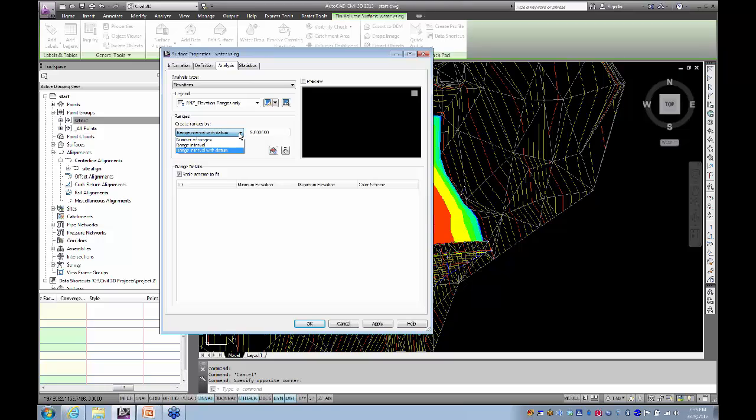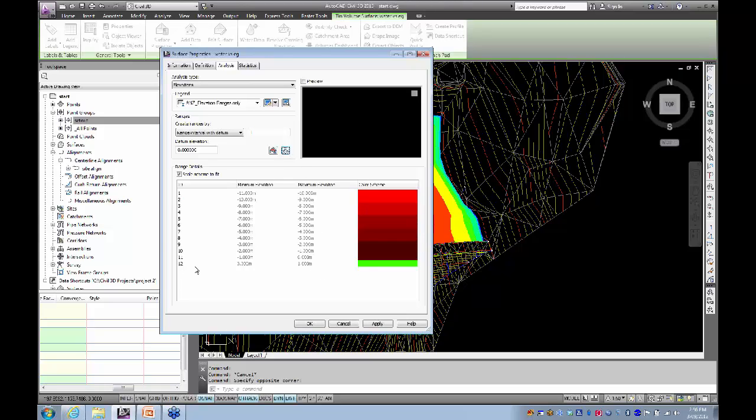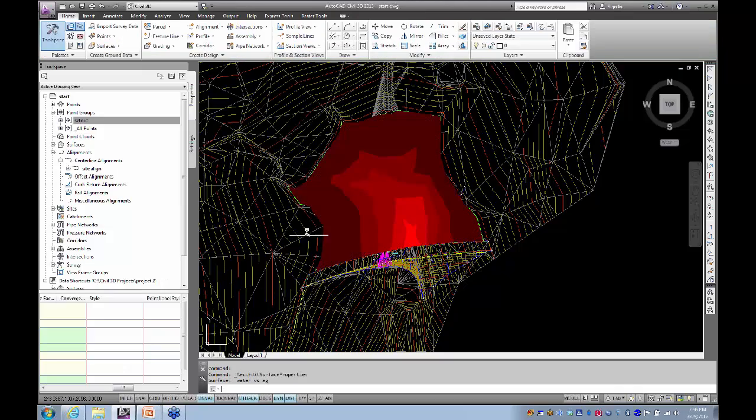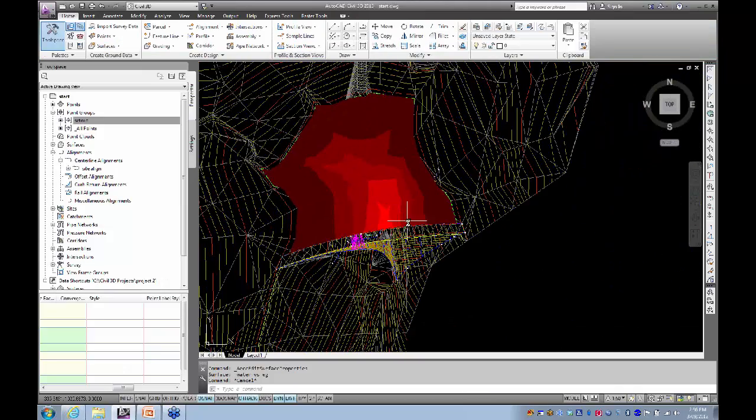We've got some different options here that we didn't have before. We can make a range interval using a datum. Let's say, let's give us volumes every 1 meter with a datum of 0. We've got a tiny little bit of fill around the edge, just where that boundary is running around the surface. And we're going down to about 11 meters deep. Now it's doing all red, so we go OK. And there's our 1 meter banding.